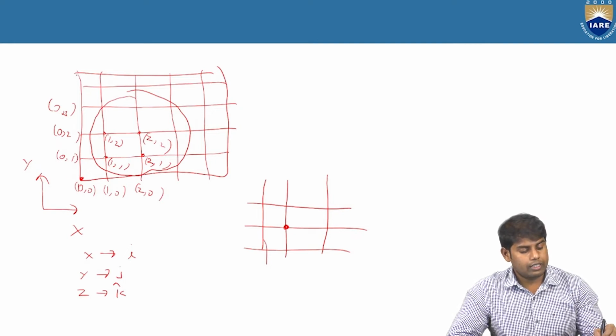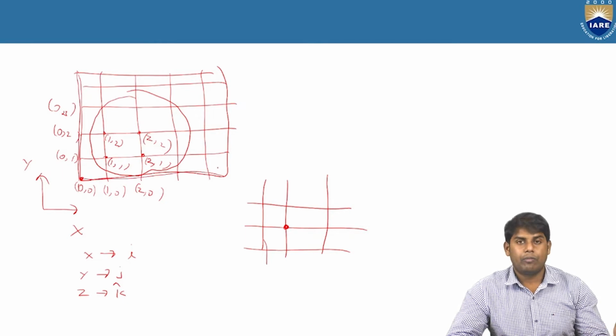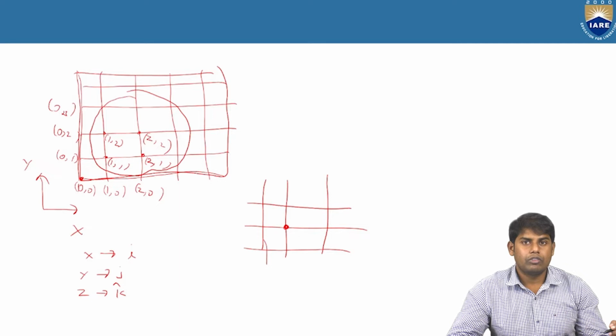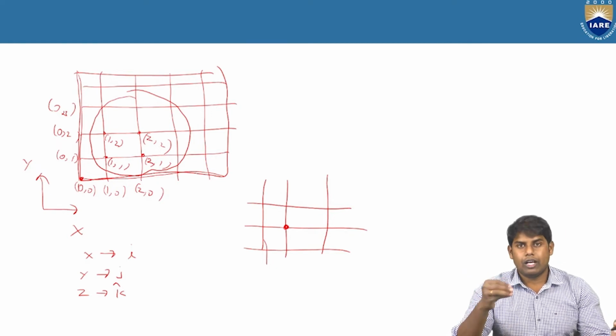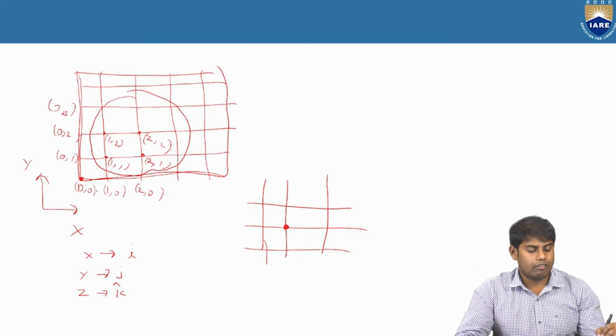Here these are called the boundary points. The boundary condition would give you the values at the boundary edge, so no special attention is required. Why? Because when you are initially starting the simulation, you assign the velocity, temperature or pressure along these boundaries, so the boundaries will have values. The grid points associated with the boundaries are called the boundary points or boundary nodes, and inside the domain these are called the interior nodes or inside points.